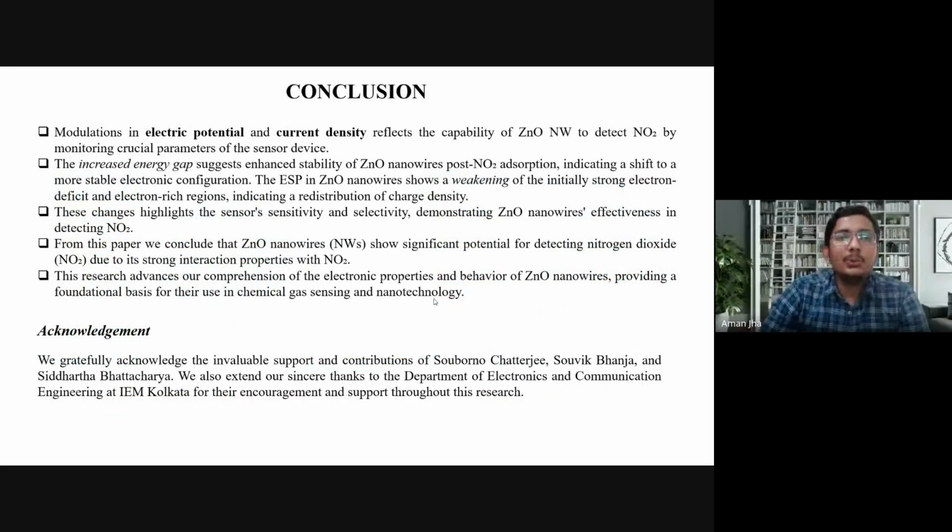Yes. Now, in our conclusion, we monitored crucial parameters like potential, current density, HOMO-LUMO energy gap and ESP plot to find out the sensor sensitivity and selectivity towards NO2. And we found out that yes, zinc oxide nanowire not only responds to it, but significantly responds to nitrogen dioxide gas when it comes in contact. This research also advances our comprehension of how the electronic properties and behavior of ZnO nanowires change with adsorption of different gases.